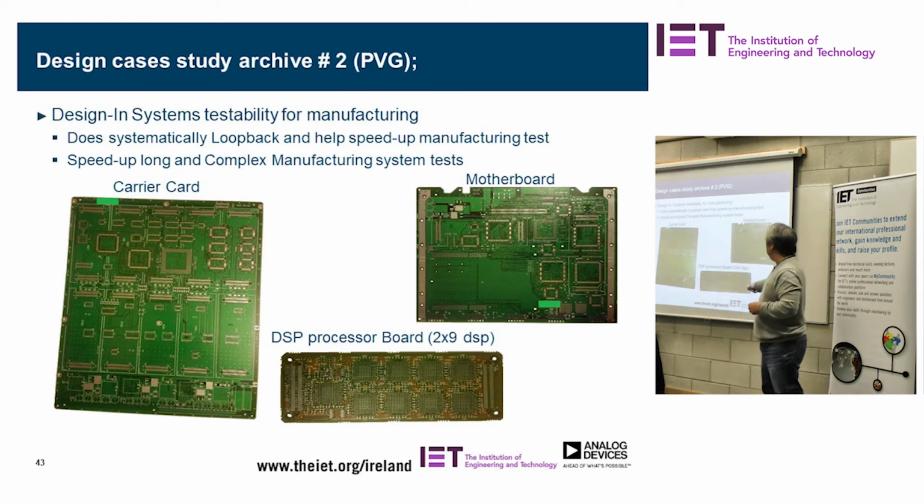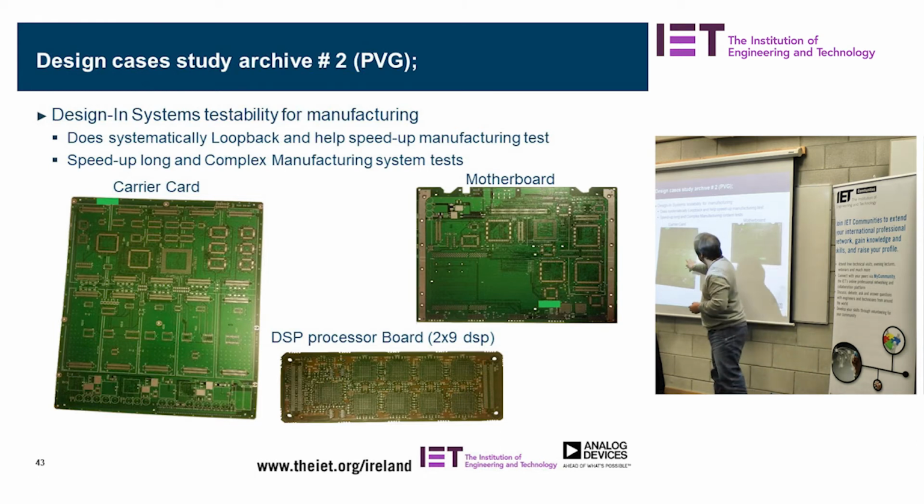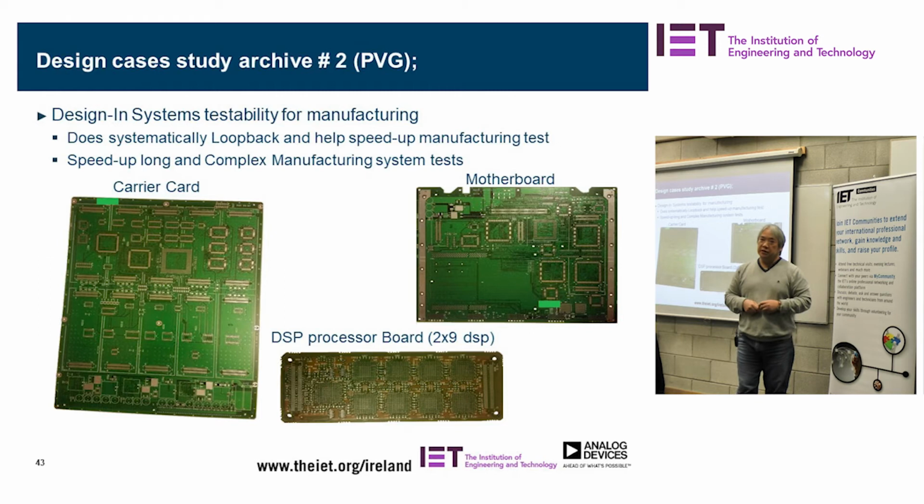So this PCB has 9 DSPs on one side and 9 on the other side. Each DSP is 1 square inch with 100 pins. The design at that time was about 1.8 volts for the core. So here's 1.8, 2.5, and about 3.3. This board with 18 DSPs plugs into this unit, and you can populate 10 of those, and then 2 on here. So on the DSPs alone, you have 200 DSPs, digital signal processors, with 100 pins.